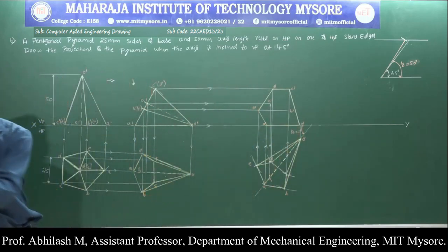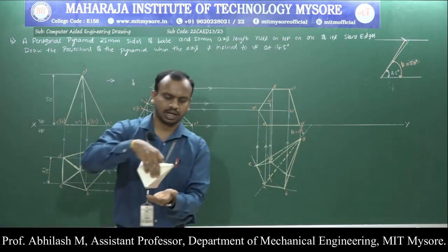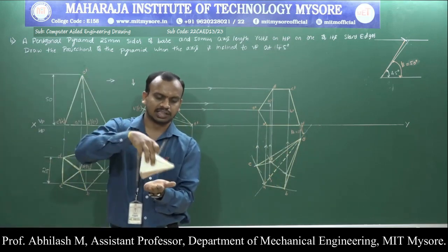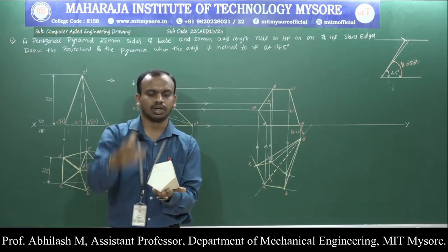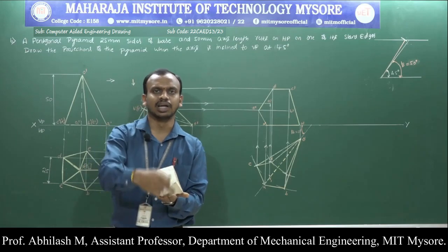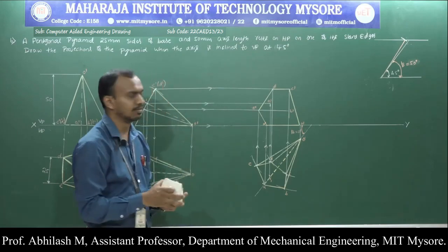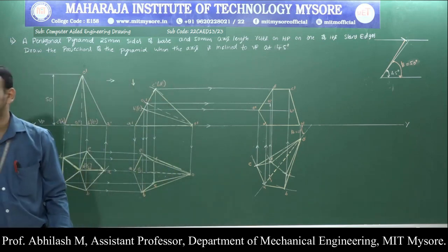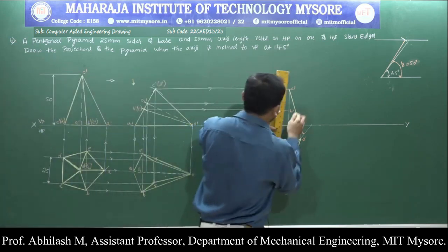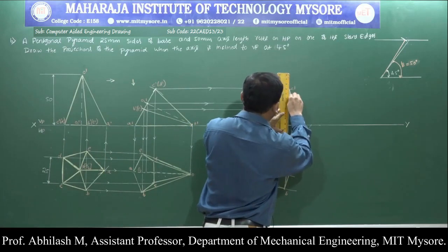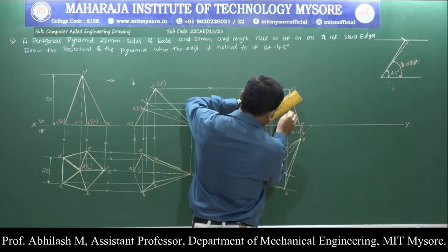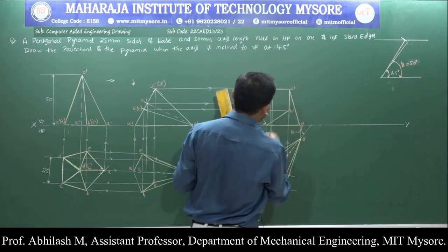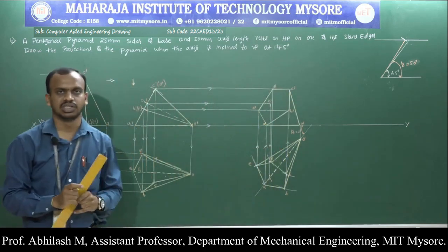The other condition is such that I have placed my pentagonal base initially here, then the slant edge resting, now for the inclination of 50 degrees, and from the observer's look, he can clearly see the complete base. So we are supposed to connect all the base. From C to B, it is completely visible. That is from C dash to B dash. Similarly, from B dash to A dash also, it is completely visible. C dash to A dash also completely visible.